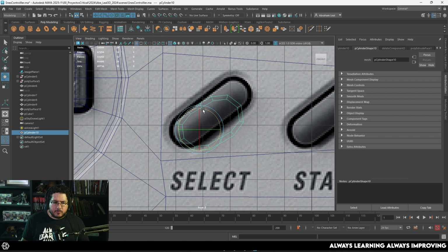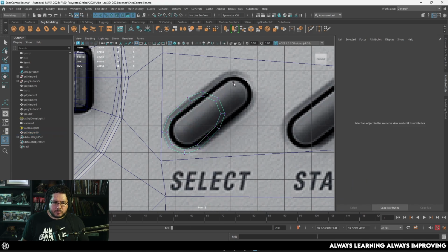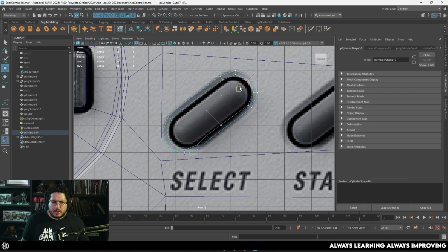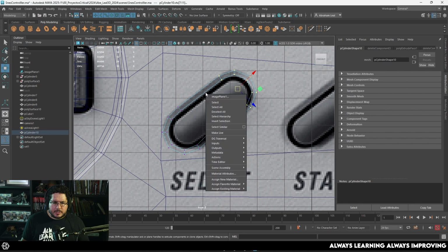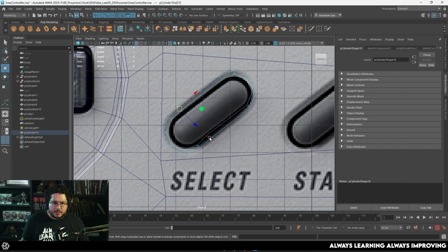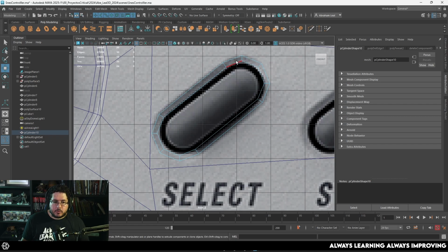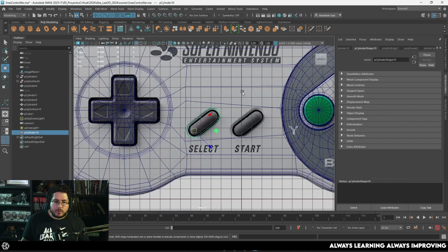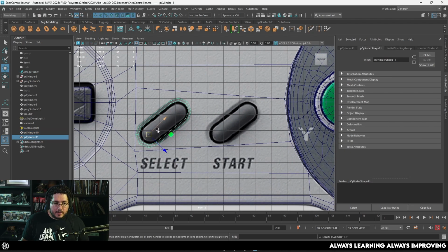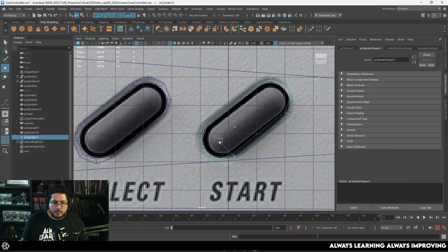As you can see, it's pretty much 45 degrees. It's not exactly 45 degrees, but close to it. So right around there. I'm going to grab this vertex right here, push them up here, and these initial edges that we added here, we don't need anymore, we can delete. And that's it. As you can see, we've created the edge loop, or the border that we need for those particular slots right there. We know that once we extrude down, like what we did on the previous sections, we're going to have the exact same effect. So this one goes right there as well.